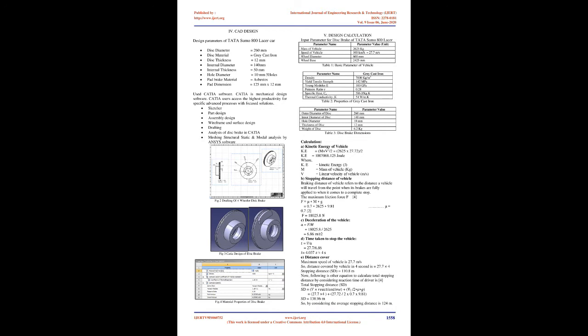3. Methodology. The methodology involves the technology utilized for performing the design and analysis of the object. Design of four-wheeler disc brake, dimension specification, analysis of disc brake by ANSYS, static structural analysis and modal analysis for mode shape. Static structural analysis of the disc brake is performed under existing boundary conditions to obtain deformation and von Mises stress, and an optimized model from topology optimization. The best optimized model is obtained from the topology optimization technique and compared to the existing model.